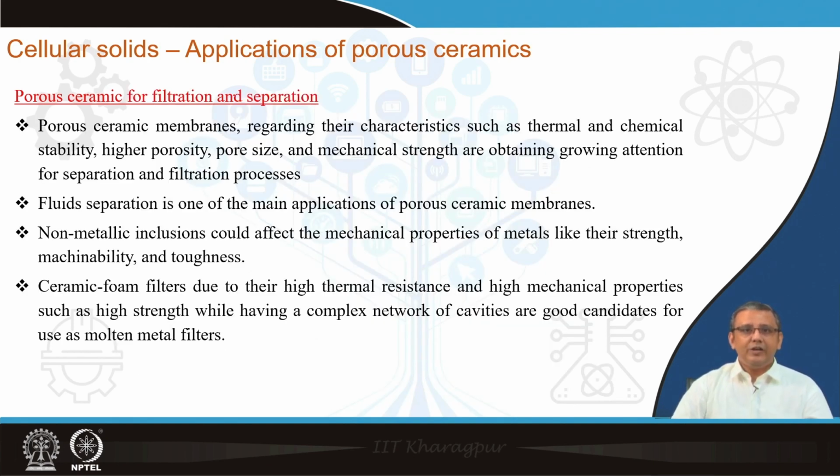Porous ceramics are also excellent for filtration and separation purposes. Now, filtration is very useful for many applications, typically in metal fabrication and metal casting, because as we know, non-metallic inclusions like oxides can affect the properties of the metals like the strength, machinability and toughness.